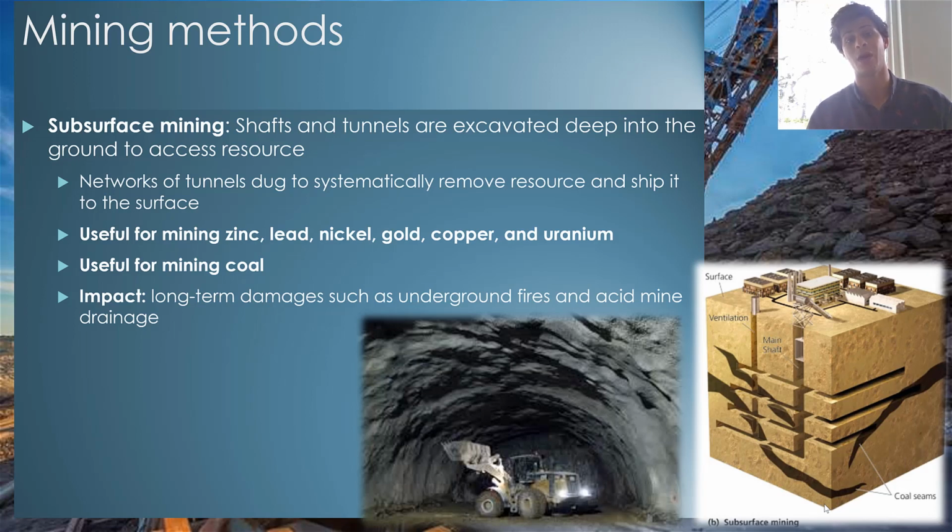Acid mine drainage is also a severe problem with subsurface mining, particularly because when you are doing subsurface mining, you are very, very close to the groundwater. So whenever rainwater gets into a subsurface mine, it basically reacts or interacts with the mineral that you're exposing, as well as some of the byproducts, so that's sulfur dioxide, for example, and then it will essentially seep directly into the groundwater, especially when you are that deep into the ground. There's not that big of a membrane or a barrier between where the mine actually is and where the groundwater actually is. So this can be a particularly big problem here.